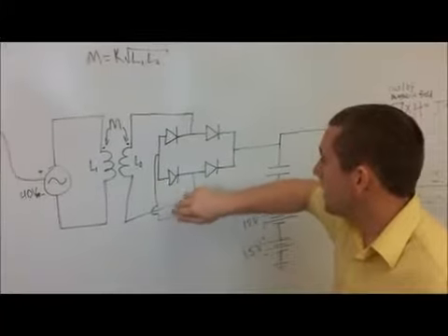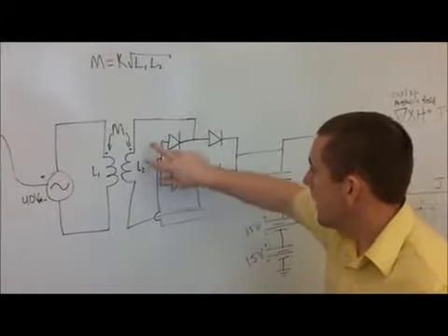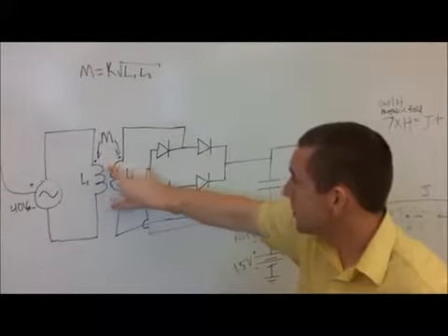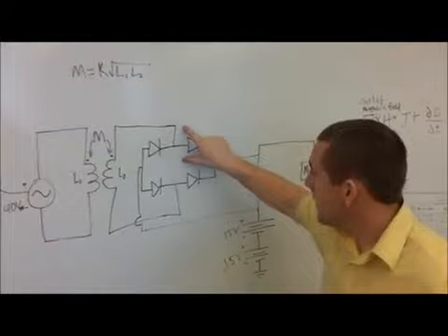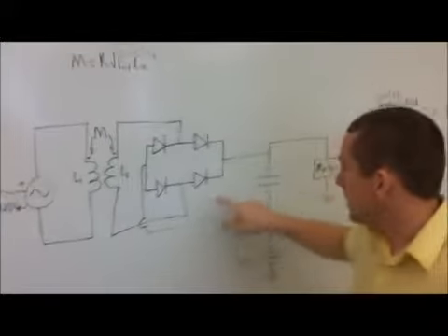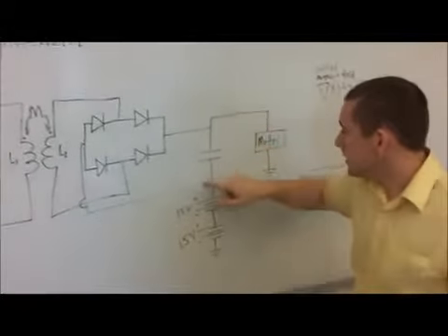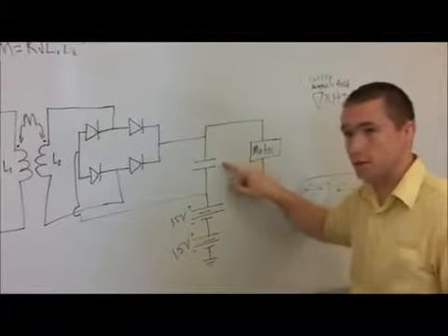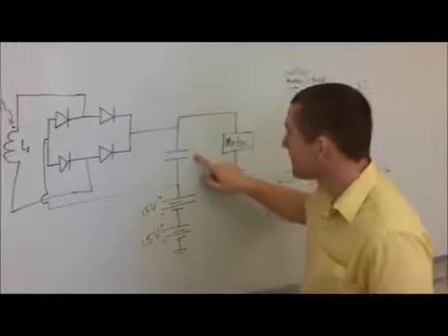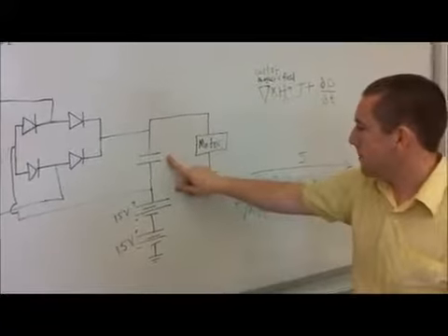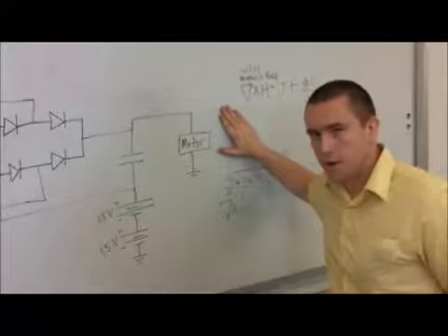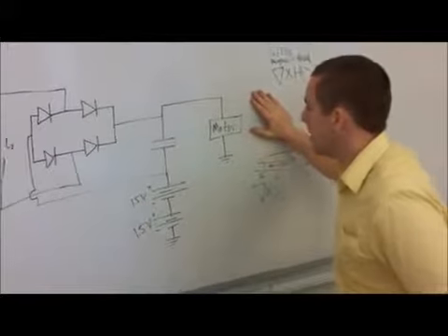We took that AC signal from these coupled coils to a rectifier. Then we got a DC voltage out of that using this capacitor. We actually use a 1 farad supercapacitor there. And this car was designed to run off of 6 volts.